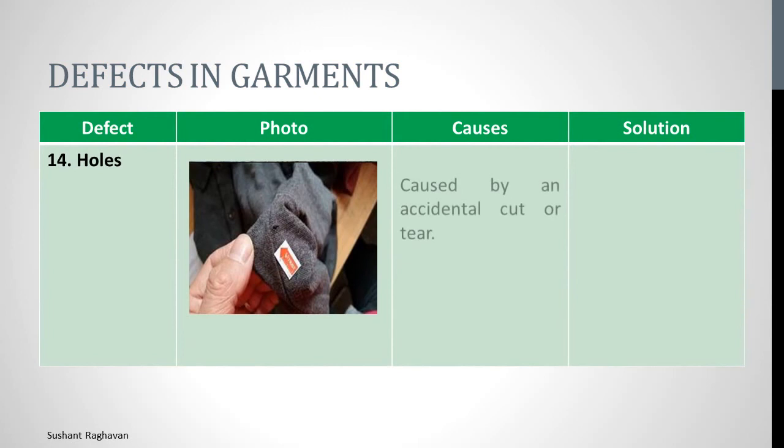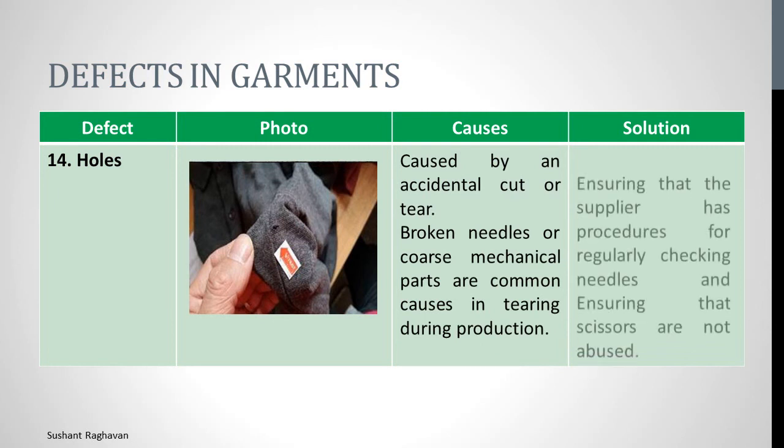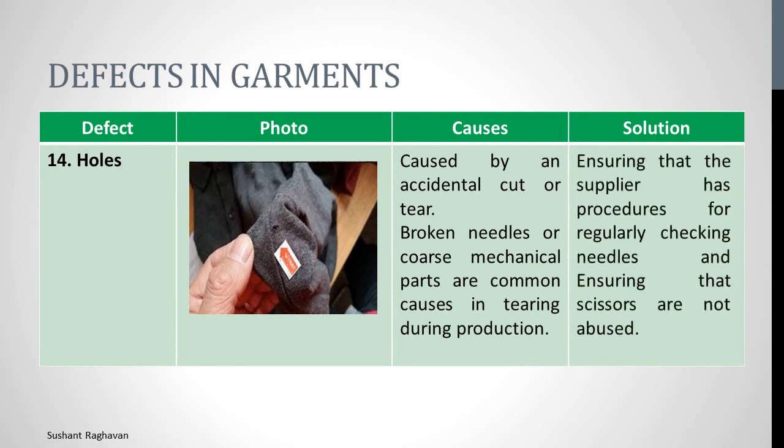Holes. Caused by an accidental cut or tear. Broken needles or coarse mechanical parts are common causes of tearing during production. Ensure that the supplier has procedures for regularly checking needles and ensuring that scissors are not abused.